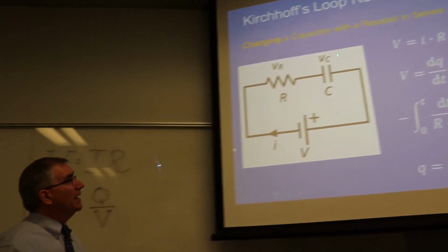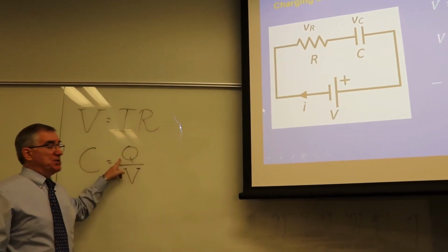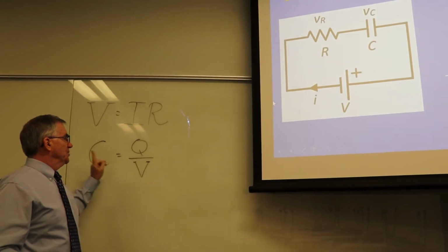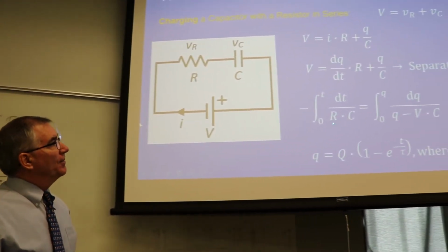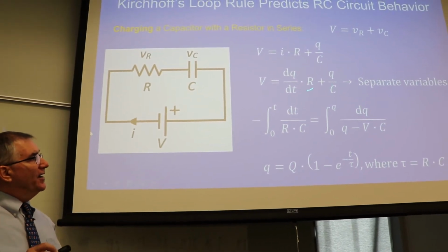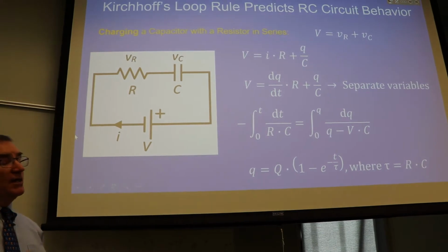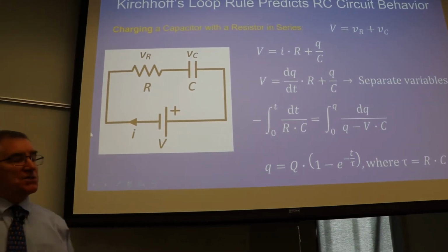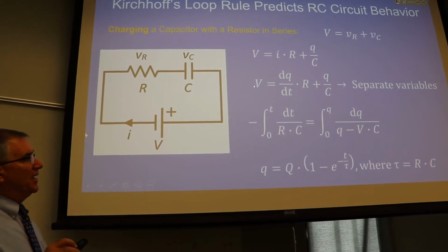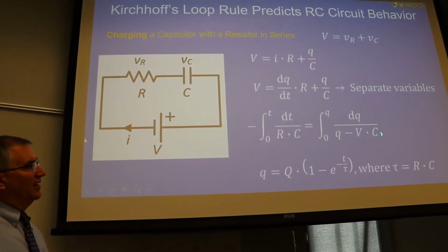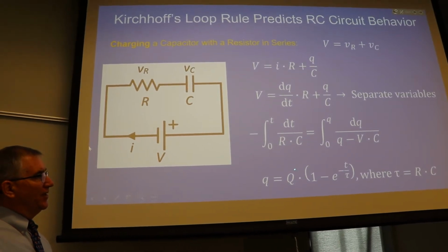So once a plate gets totally charged up, then you can see over here on this equation, Q is equal to voltage times capacitance. So I multiplied both sides through by C, and then R and C are together here, RC. That's a very important number. It's called the time constant of the circuit. And then C is over here with voltage, and that becomes big Q. Right now I left it as just V times C, but then it'll become big Q down here.